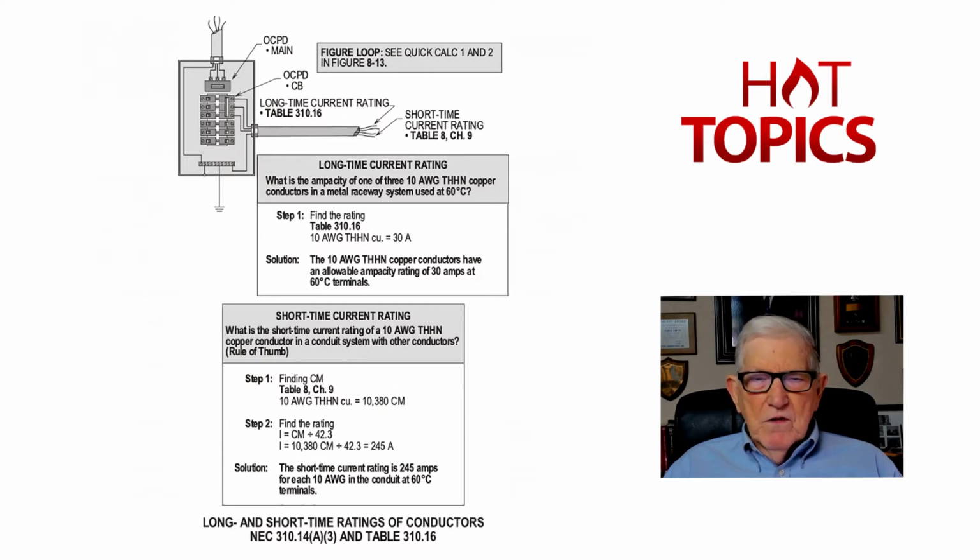And of course, in the solution, we look at 240.4(D), and if it's not one of the loads that require the overcurrent device to be sized greater than 125%, which we, from our experience, know that all those loads where you can size up greater than 125% are found in Table 240.4(G) of the code.